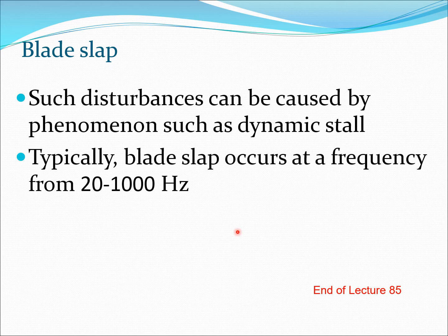Noise prediction is rather difficult. There are comprehensive theories on this. So acoustics itself is a vast discipline as far as helicopters are concerned. The source of the acoustic noise here is essentially the fluid mechanics. So we need to study the fluid mechanics in detail to figure out the various aspects of rotational noise, blade slap, as well as vortex noise. Especially vortex noise and blade slap would require good levels of fluid mechanics, which would, for example, require use of sophisticated theories including computational modeling of the entire flow field and so on.